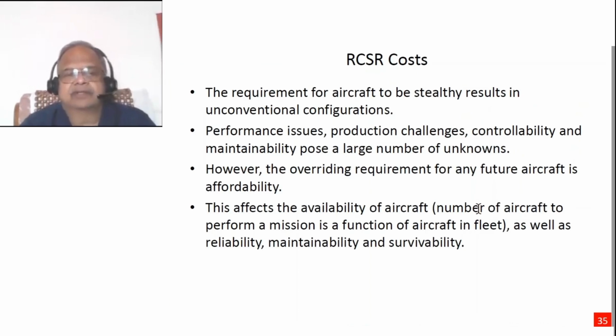So the requirement for aircraft to be stealthy results in very unconventional configurations, because you are at the same time addressing observables: acoustic, optical, infrared, radar cross section. And these throw up a lot of performance issues, production challenges, controllability and maintainability. All this poses a number of unknowns.